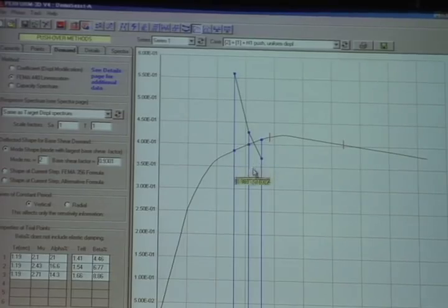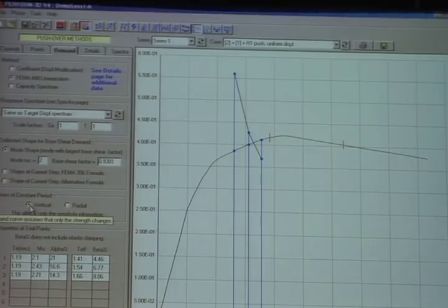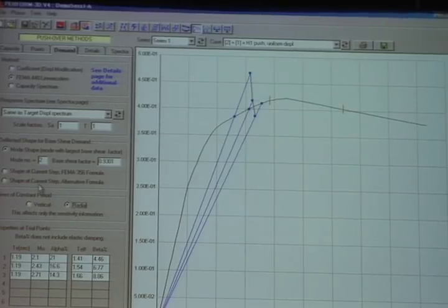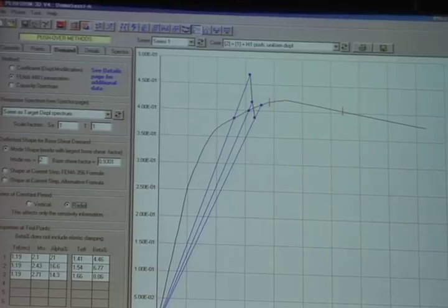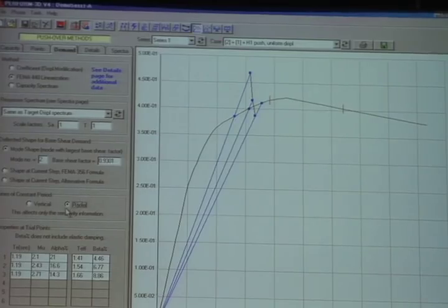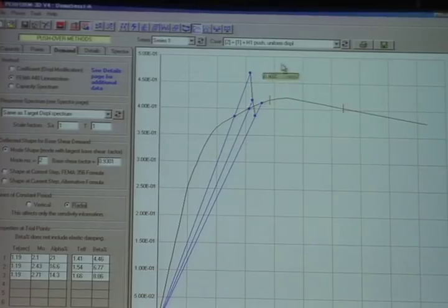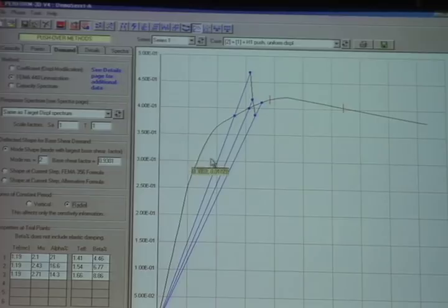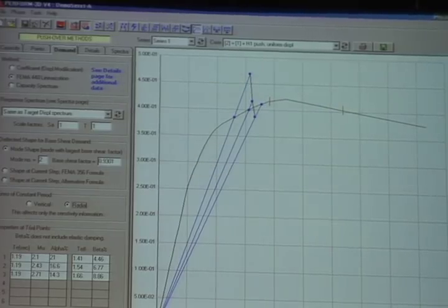And that, notice here, says vertical. If I make this one radial, this is a little bit different. What this says is that let's keep the stiffness constant, but just increase the strength. So you would expand this curve out radially rather than vertically. And what this says, if you just increase the strength without changing the stiffness, it's not going to make too much difference in the target displacement. However, the curve will be rather different, so it'll be further back on the curve. Without going into details, this gives you some sensitivity information.